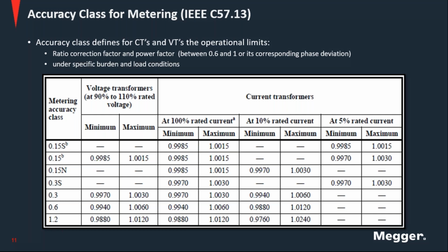factor. Now, this is in relation to the construction of the CT, and this is what the manufacturer guarantees, but this also depends on what is connected to that instrument transformer. So these instrument transformers do not deliver power, but they definitely have a load connected to them. They have a circuit that is basically composed of the wiring and the metering and control devices.